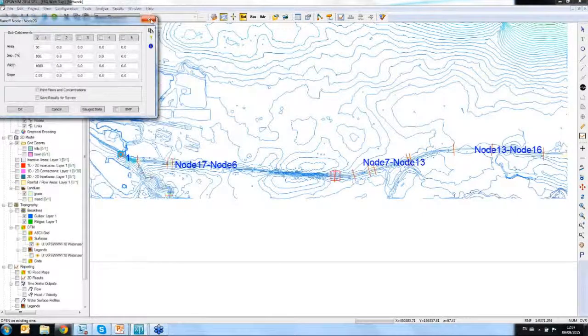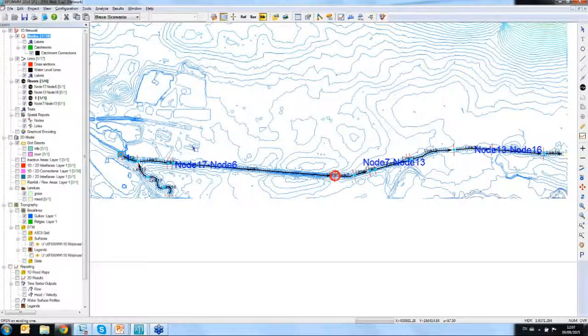I'm not going to stop on how to set up a river and how to add inflows, because we did cover it in webinar number 1 and number 2 of our series. But what I will do now is show you how to replace a natural section with a man-made section, a culvert. And then we will run the model live, and we will see what happens when a culvert is there, and we will check if the proposed size of the culvert is good enough to convey the water. If it is not, we will ask the software to resize the culvert based on our requirements, and then we will make this culvert blocked and see the consequences.